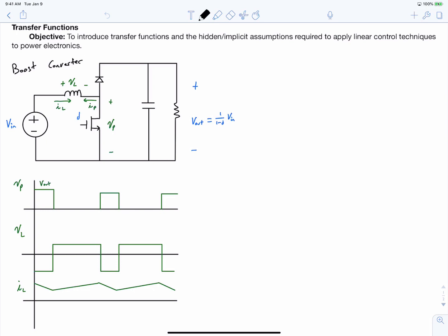We've previously talked about the notion of regulation, of line regulation and load regulation, where we talked about changes in output voltage due to changes in our line voltage, or changes in output voltage due to changes in our loading condition. That is, if our effective load resistance suddenly changes and our output current varies, our load voltage may vary as well.